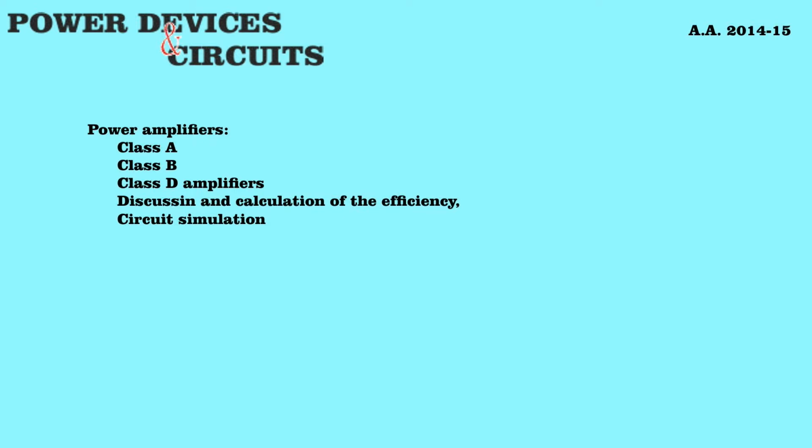Imagine that you want to drive a loudspeaker, a speaker for audio amplification. The typical input impedance, let's say, is in the order of some ohms, let's say 5 ohms. The loudspeaker will be driven with 50 volts, it's not a very high audio power. Which are the peak voltage and current that the BJT needs to handle?